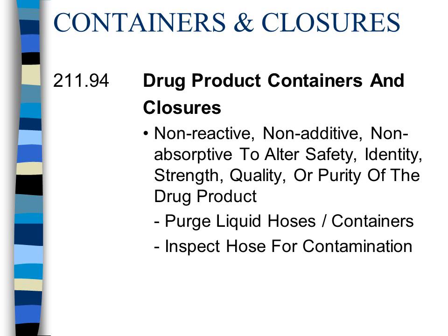By purging your hose, you just open up very carefully the liquid oxygen valve on the supply vessel and let a flow of gas go through your hose. That's after you remove the plug. Prior to doing that, please inspect your hose for any contamination.